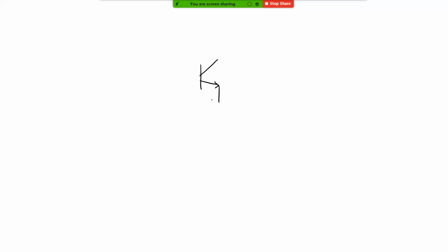This is my transistor. Let's say now you are in the lab. You have the transistor in your hand. I am giving you a beta of, let's say, 200. And I am now having RC. My task right now is to make sure that this BJT is having a transconductance of 10 millisiemens or 2 millisiemens. So either 50 microamp of current or 250 microamp of current, I have to make it flow. Where do you want to put the current source?